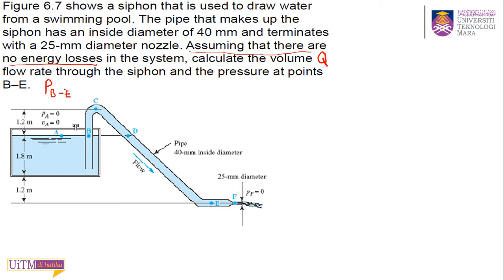It's very easy. It's not too complicated. First, as I always suggest, write the continuity equation. So A1 V1 equals A2 V2. Continuity equation, remember Q1 equals Q2. And you can rearrange your equation to V1 equals A2 V2 over A1. So this is your first equation.